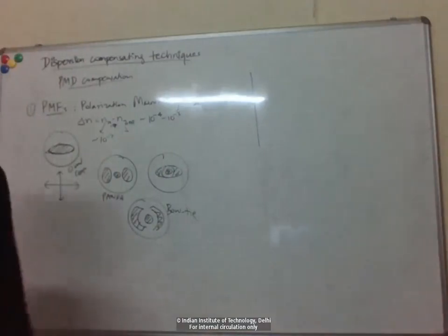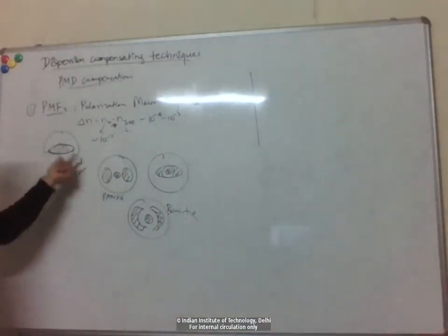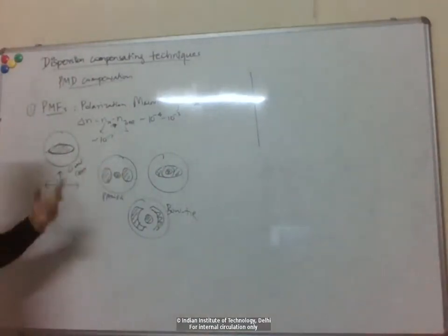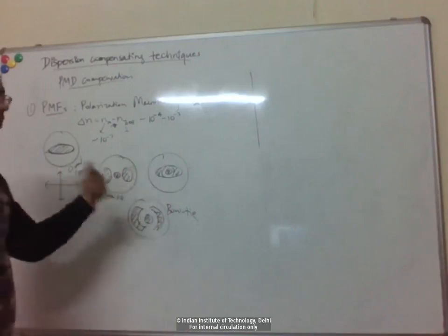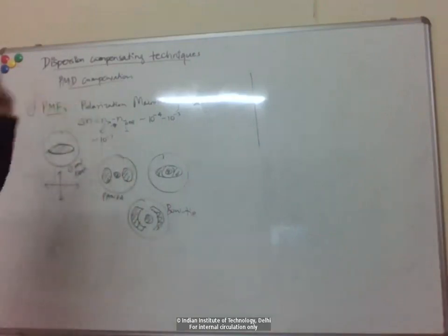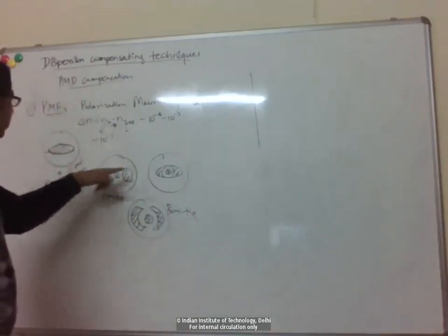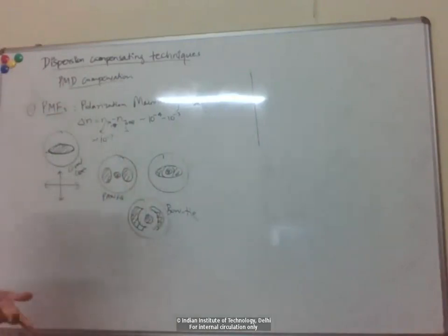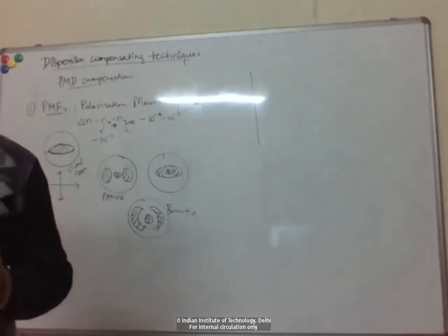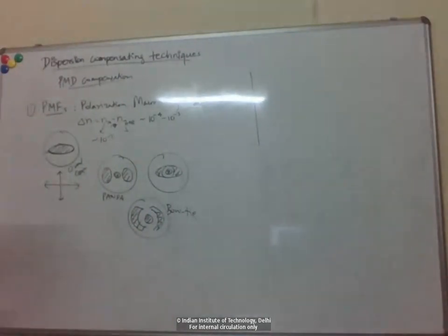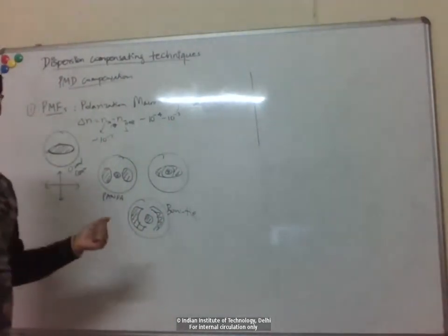But of course, you can see that these are very complicated, right? So typically they'll have much higher loss than single mode fibers. Also, their chromatic dispersion will be worse than single mode fibers, right? Although you've now eliminated PMD, each of them will have their own chromatic dispersion because of these complicated structures, which may be even worse. Okay. So polarization maintaining fibers are not a practical solution.